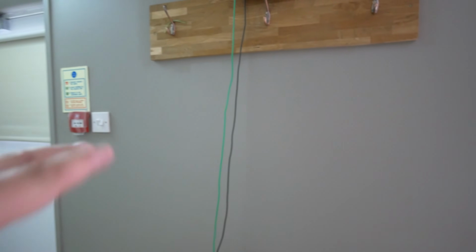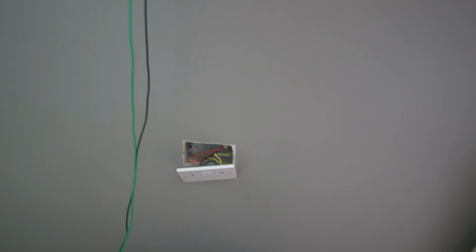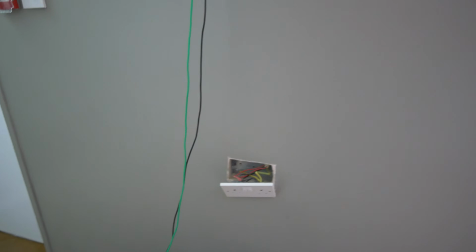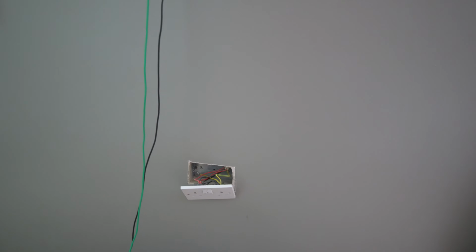We're going to open up some of the light switches and light fittings as well, some of the other sockets. Make sure the terminations are all in good order and there's nothing looking out of place. The best form of approaching an EICR is using your eyes and having a good poke around, especially in a small little setup like this.